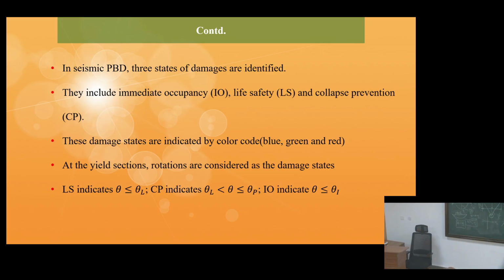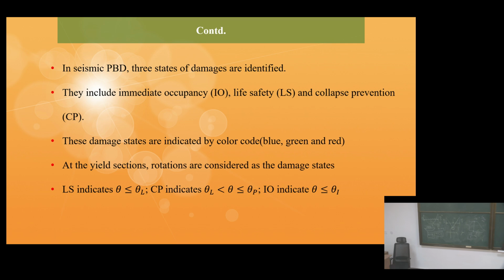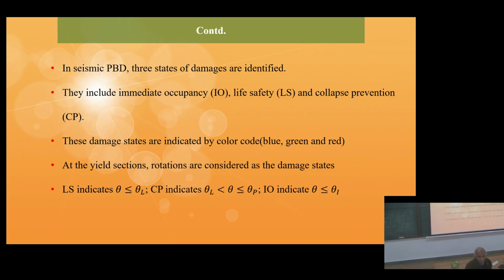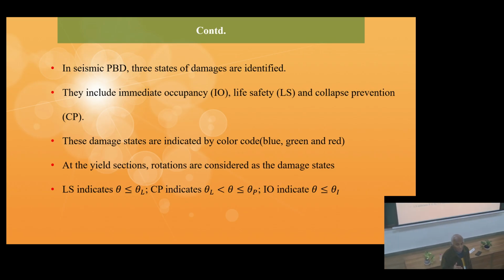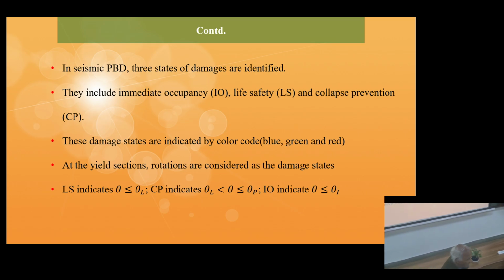Now, when we do a seismic performance-based design, many people can say that I will not allow the performance point to go beyond IO. IO means immediate occupancy. If an earthquake comes and goes, the structure will have minor damages and people can get in easily.